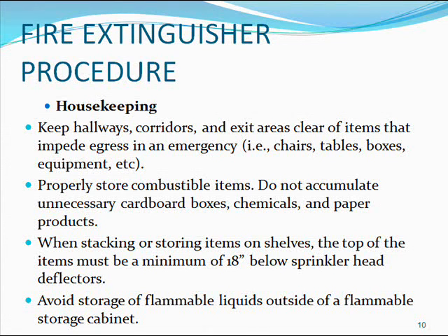Housekeeping. Keep all hallways, corridors, and exit areas clear of items that impede progress in an emergency, for example, chairs, tables, boxes, equipment, etc. Properly store combustible items. Do not accumulate unnecessary cardboard boxes, chemicals, and paper products. When stacking or storing items on shelves, the top of the item must be a minimum of 18 inches below sprinkler head deflectors. Avoid storage of flammable liquids outside of a flammable storage cabinet.